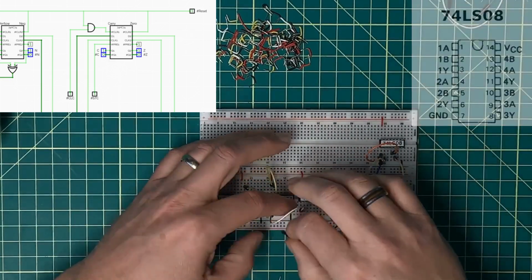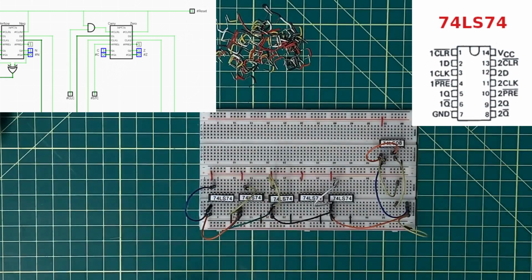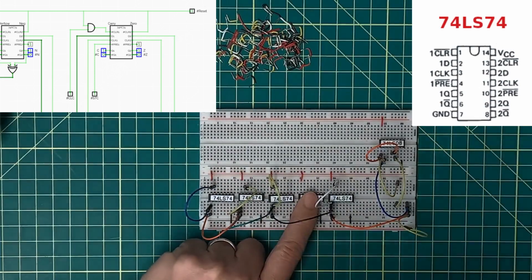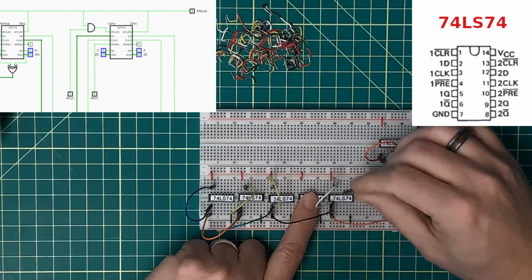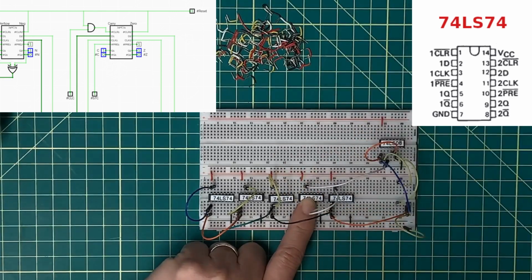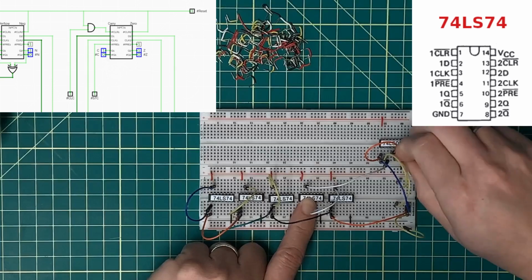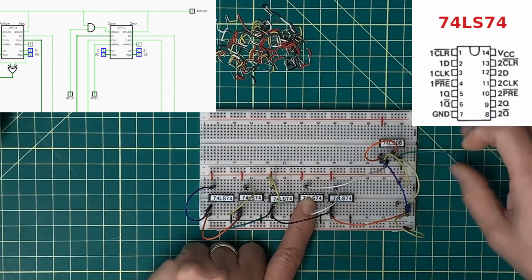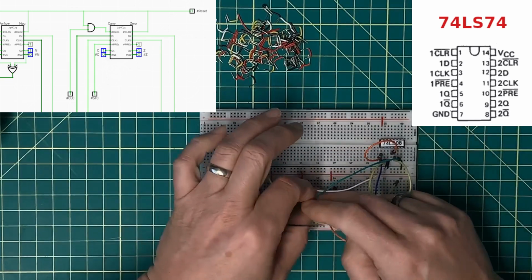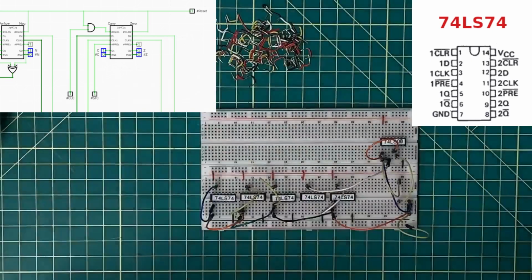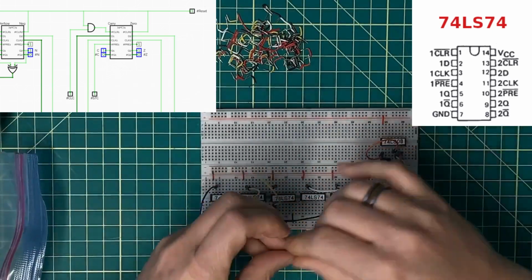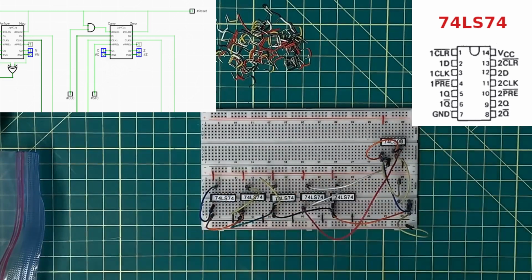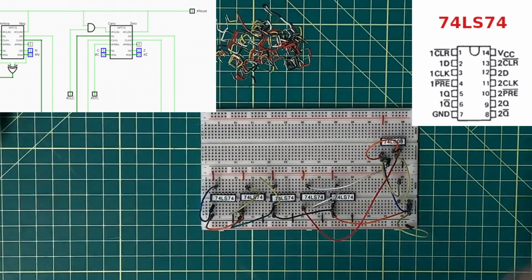And then changing this, if this is going to be the IC I use for carry, the output of this upper one is going to go to the upper clear, and then the one that's coming off the lower is going to go to the lower clear, and I need a longer hookup wire for that one. So the lower is going to come down here to the lower clear on pin 1.